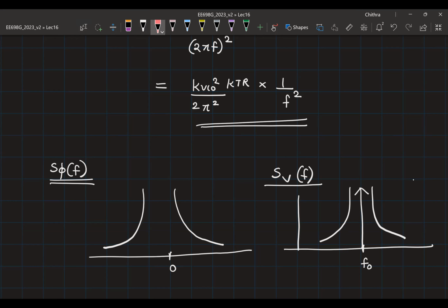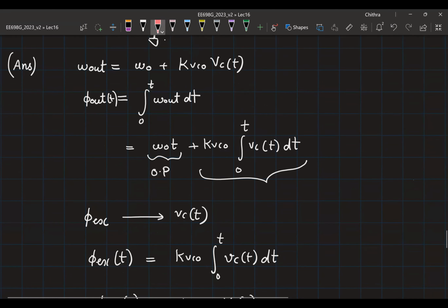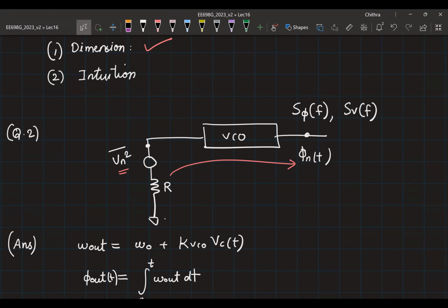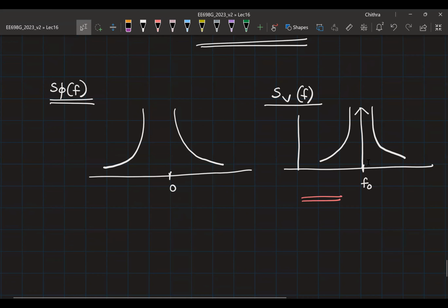Again, this figure you have here is also not in line with the intuition we have, right? Because after all, this is simply an oscillator. The oscillator is oscillating, just that we know its f0 is going to vary around a few values around f0, right? On an average, it is still an oscillator. But it looks like, one, we have an impulse at f0, and two, this phase noise is increasing, correct? The power around f0 is also very, very high. So that doesn't make intuitive sense, right?